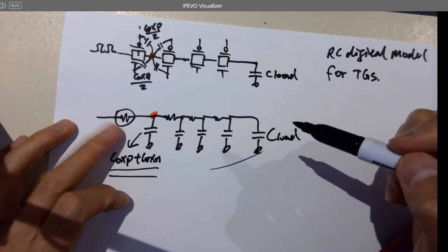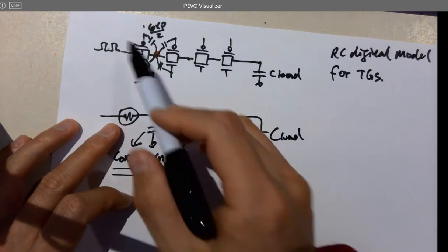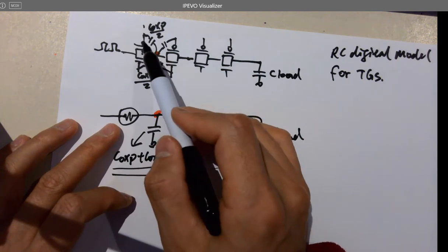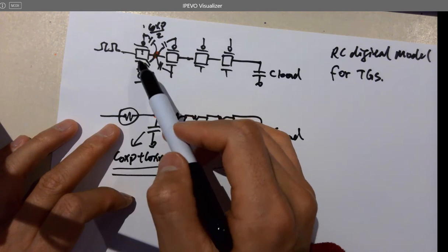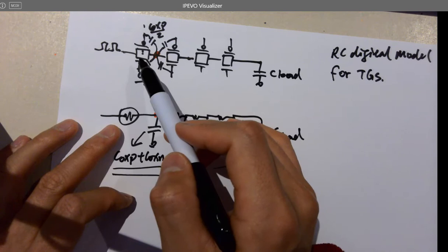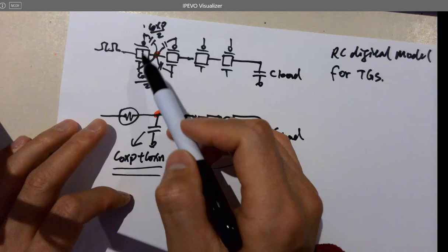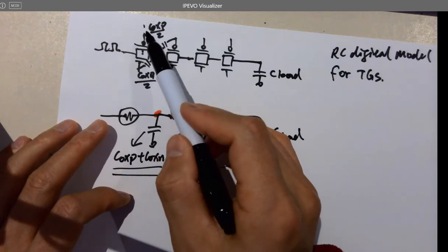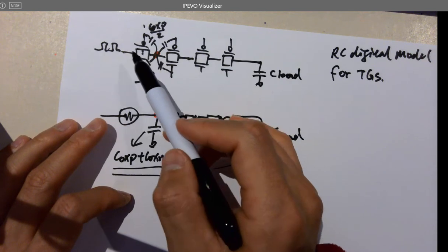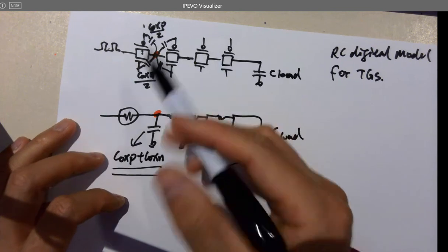What's a resistor you can model here? Whenever the signal is being transmitted from here to here, which one is on, which one's off? They're both on. Is that correct? Yeah, they're both on. It's a transmission gate. You want to turn both of them on. So that's why you want to invert the clock, right? So when they're both on, you got current flowing through both transistors. And so what's a resistor here?